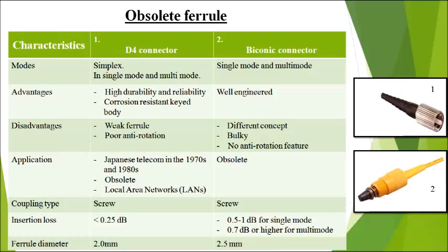The second one, the Biconic connector, comes in single mode and multi-mode. The advantage of Biconic connector is that it is well engineered. The disadvantages of Biconic connector are different concept, bulky, and no anti-rotation feature. Biconic connector application is obsolete.